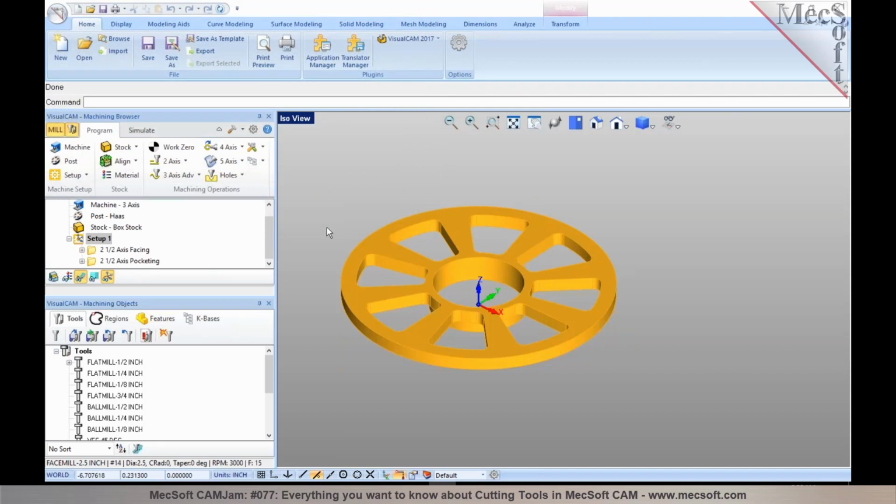Uday, I want to jump in here. One of the things about the machining time computation is actually pretty simple. All we do internally is take the length of your tool path, the entire length of your tool motions, and multiply it by the velocity of the tool, which in this case is the feed rate of the tool. So there's only two things that affect the machining time. One is the length of your tool path motions, and number two, the feed rates you've assigned.